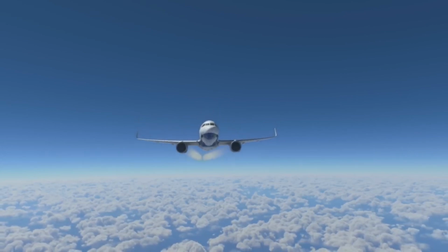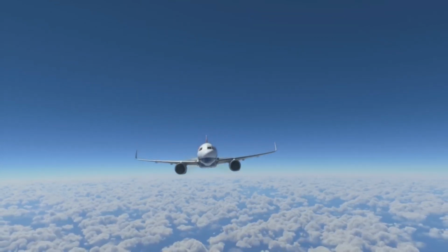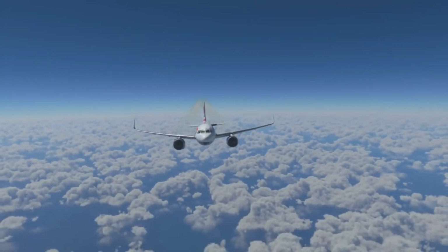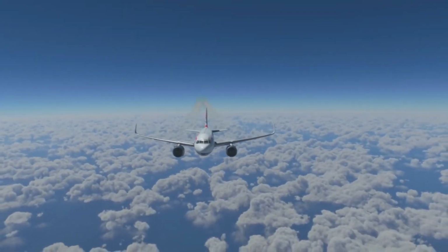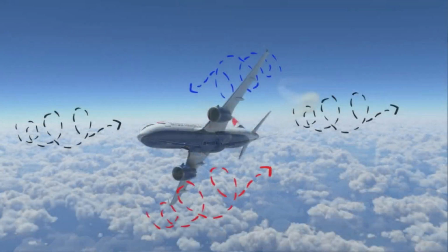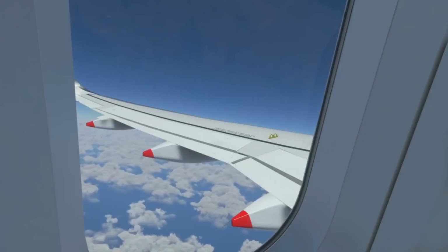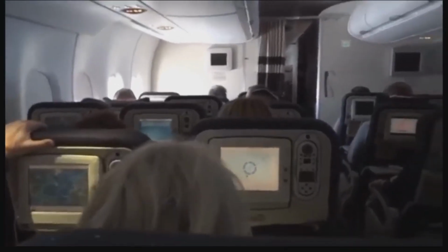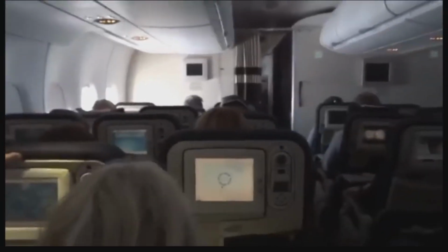To maintain control during an approach in turbulent air with gusty crosswind, the pilot should use partial wing flaps. With less than full flaps, the airplane is in a higher pitch attitude. Thus, it requires less of a pitch change to establish the landing attitude and touchdown at a higher airspeed to ensure more positive control. Pilots often use the normal approach speed plus 1/2 of the wind gust factors in turbulent conditions. If the normal speed is 70 knots, and the wind gusts are 15 knots, an increase of airspeed to 77 knots is appropriate. In any case, the airspeed and the flap setting should conform to airplane manufacturers' recommendations in the AFM/POH.